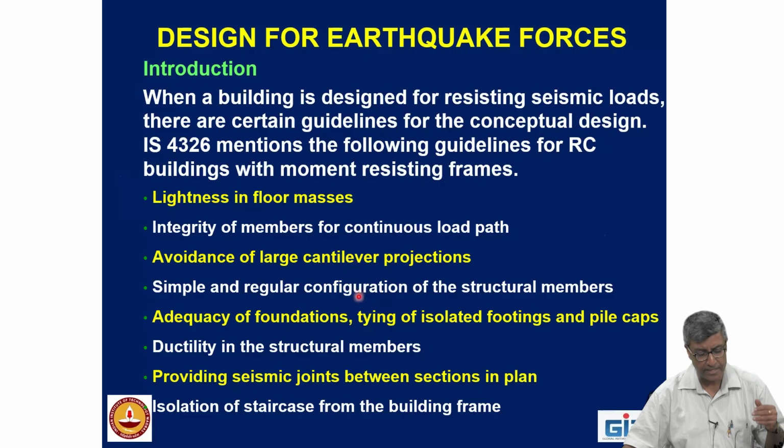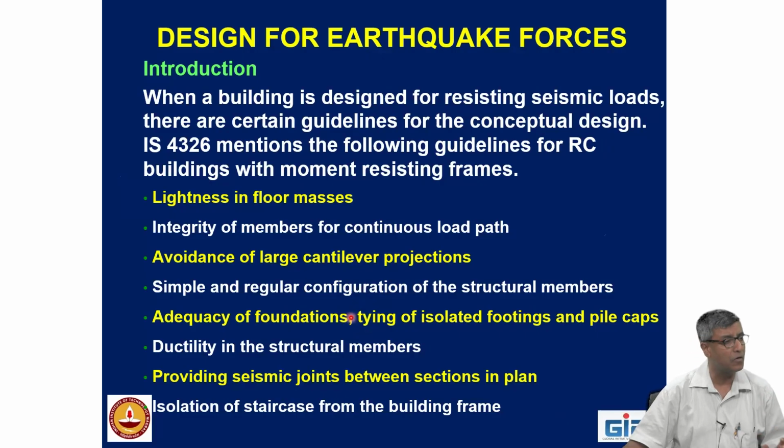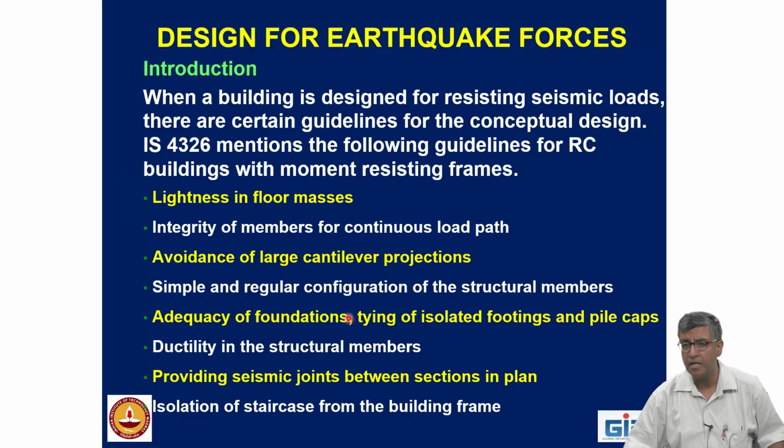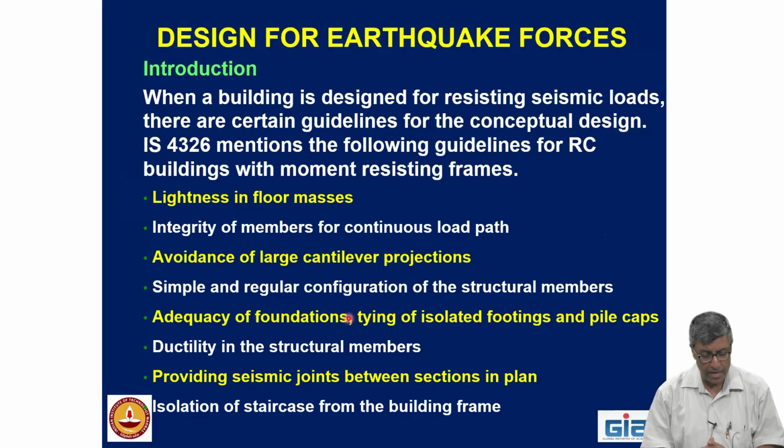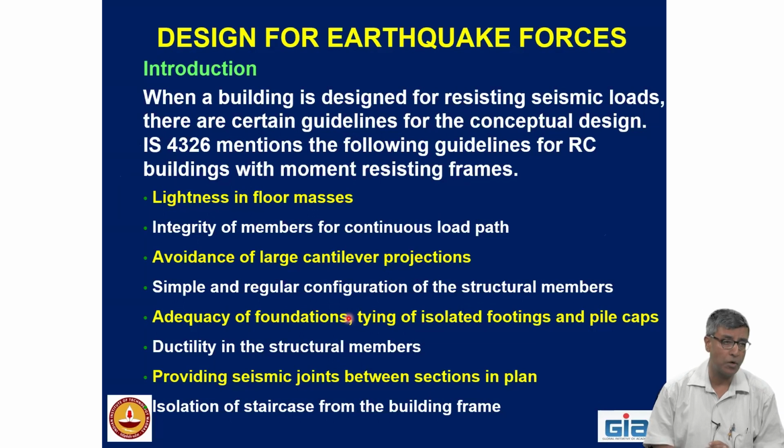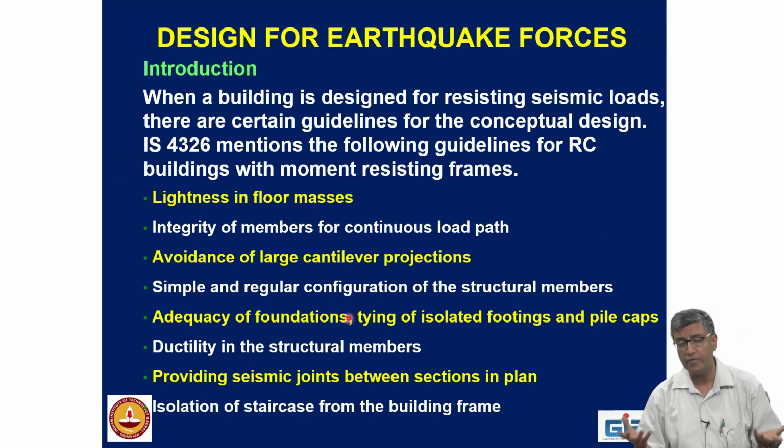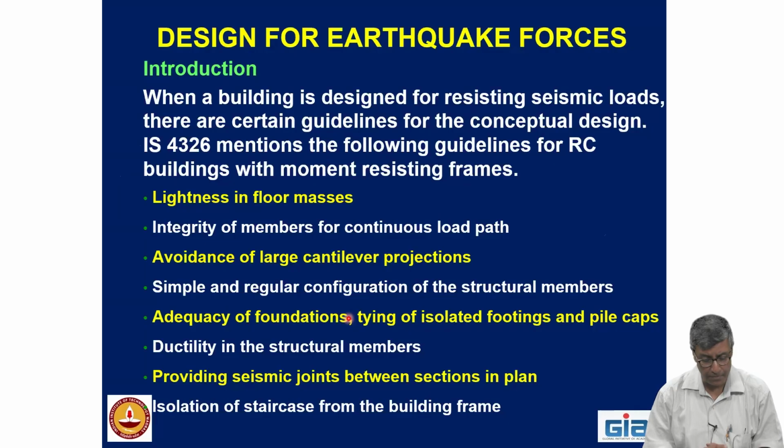Avoidance of large cantilever projections, regular in configuration. What is meant by the word configuration? How your building members are laid out. Adequacy of the foundations, very important. The taller the building gets or the softer the soil, there can be problem.